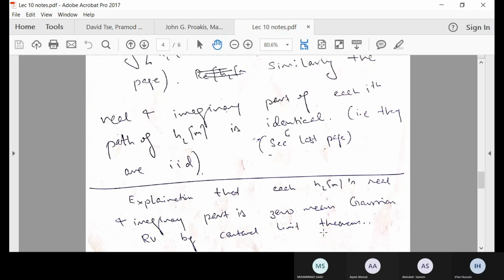So now the real part will add up, the imaginary parts will add up, and they will become a Gaussian in real. They will become a Gaussian in imaginary. They are already circular symmetric. You are adding them up, they will again give you a circular symmetric Gaussian random variable. Previous properties they will just transfer. They will now become a Gaussian random variable. So now you have a circular symmetric complex normal distribution, or you can say circular symmetric complex Gaussian random variable.